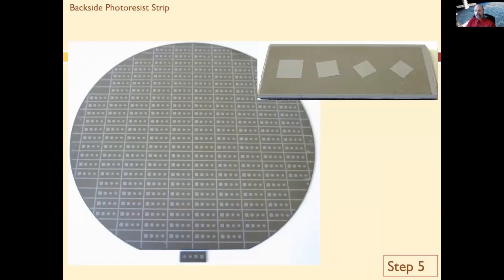So after we take the photoresist off, right, it looks like this. So you can see where the silicon nitride is remaining and where the silicon nitride has been etched away. And that's exactly what you want to do, right? So we do this a lot in semiconductors and in MEMS fabrication. You put a material down, then you put a photoresist down, you pattern the photoresist, and you etch away whatever's exposed, and then you remove the photoresist. So that's a common set of process steps. And you build layer upon layer upon layer upon layer until you get your final device created.